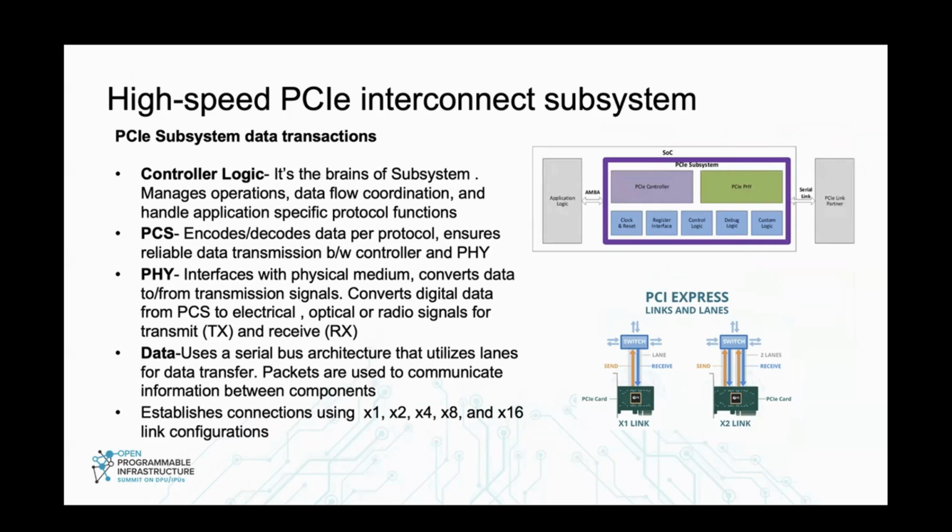Hello, everyone. I'm Rajesh. My expertise is in subsystem implementation and interconnect technology like PCIe, CXL, Ultra Ethernet, and UA-Link. I do designing and I have an exact idea of how it's going to fit into an SoC. My first slide is about the PCI interconnect subsystem. Here, highlighted in purple, are the PCI subsystem and its basic building blocks, but the strategy is the same for either Ultra Ethernet or UA-Link: you will have a controller, PHY, a clocking and reset structure, control logic and custom logic. So overall, the implementation strategy will be the same.